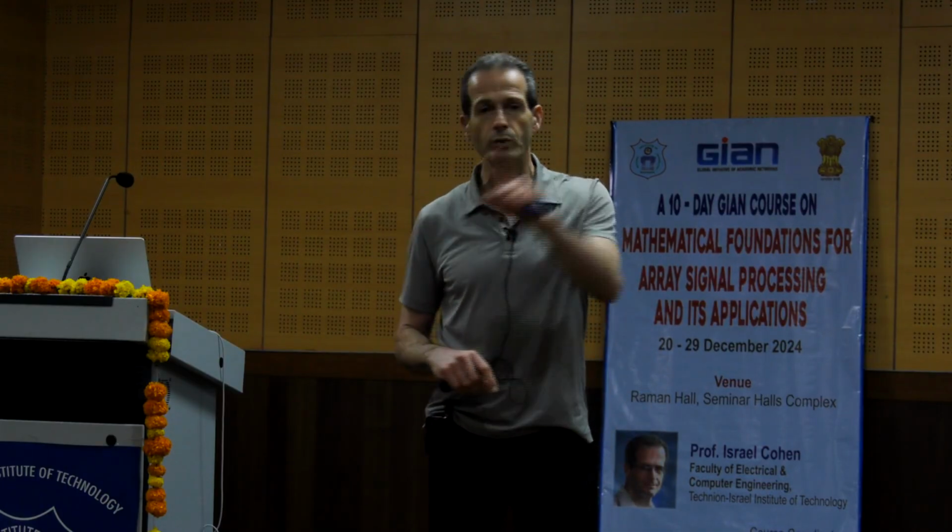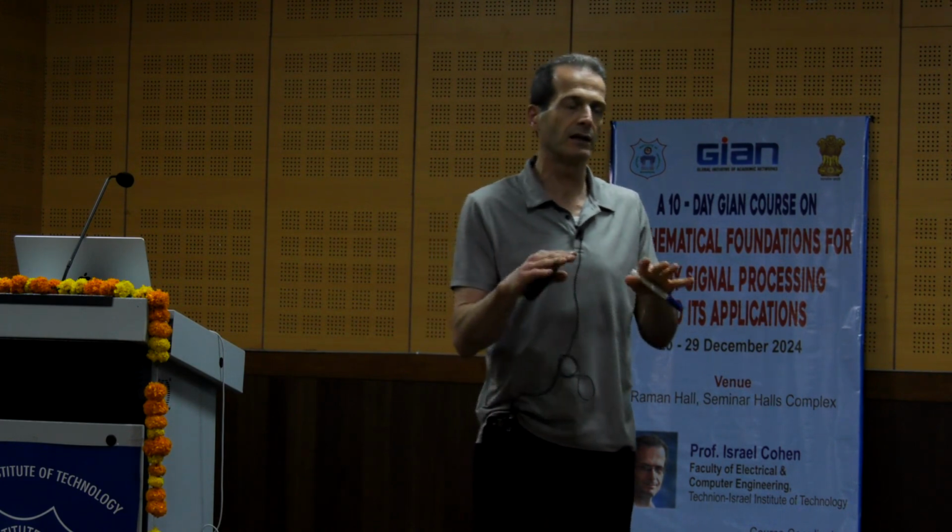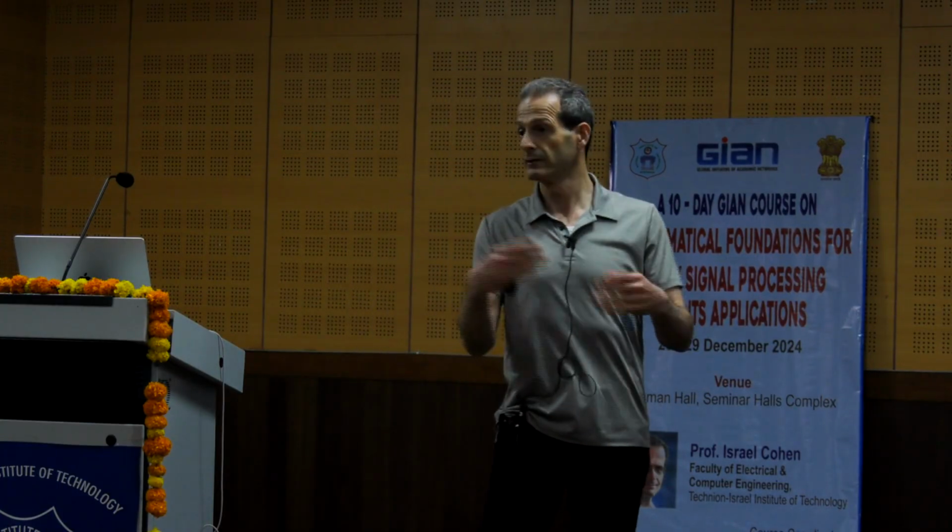But then what will happen? We will see that the white noise gain will become lower. So we need to use more expensive sensors with low thermal noise, or if we use sensors with a certain level of thermal noise, we need to limit the white noise gain.